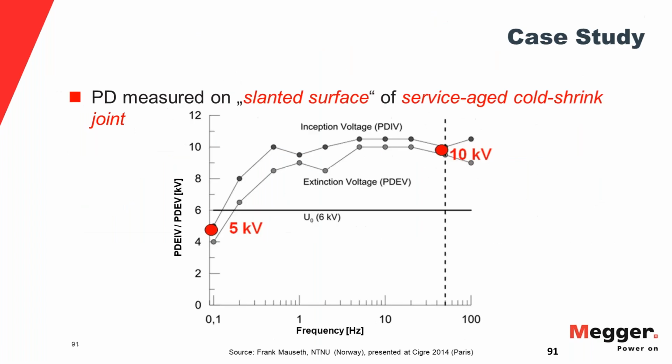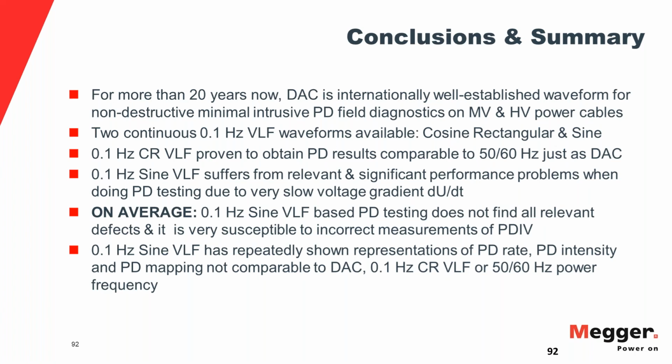And then that is a fairly recent publication that is also interesting, because it tells you, well, in these refractive field control elements in the joints, it's really important to have something that is comparable to power frequency to be able to get a correct assessment under operating voltage condition. And I believe this is the conclusion of everything. So I just made up some statements here, which were shown in the slides before.